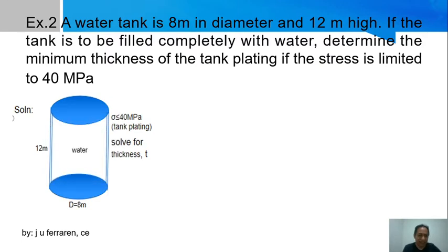Okay, see, your tank looks like this, no? So this is filled with water completely. So these are the dimensions. Then you are required to solve for the thickness. And there is an allowable stress of the tank plating which can be less than or equal to 40 megapascal.